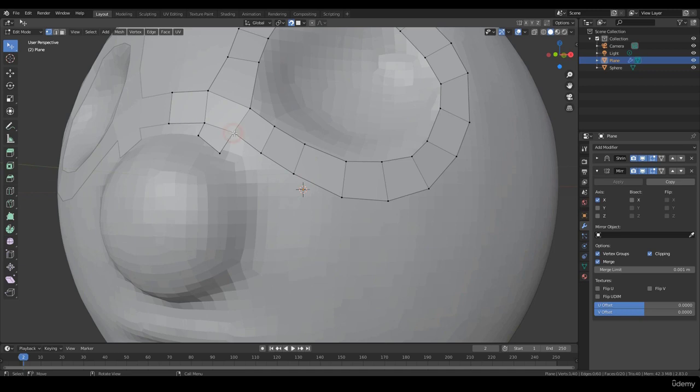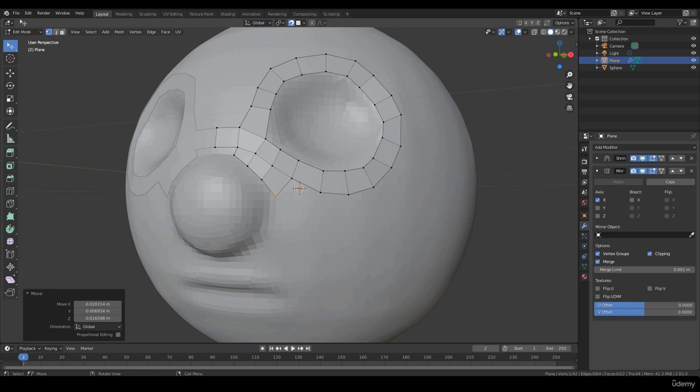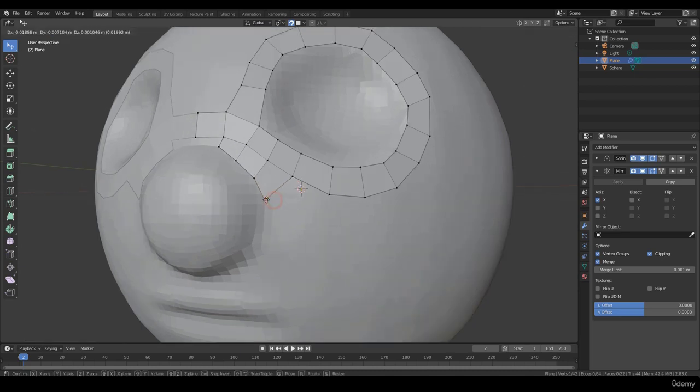So you can select the vertex and then hover your mouse over the opposite mesh on this side and press F. See how you can easily create a mesh just like that? Once again, I can click on this vertex, press F. So you can easily create geometry like that.